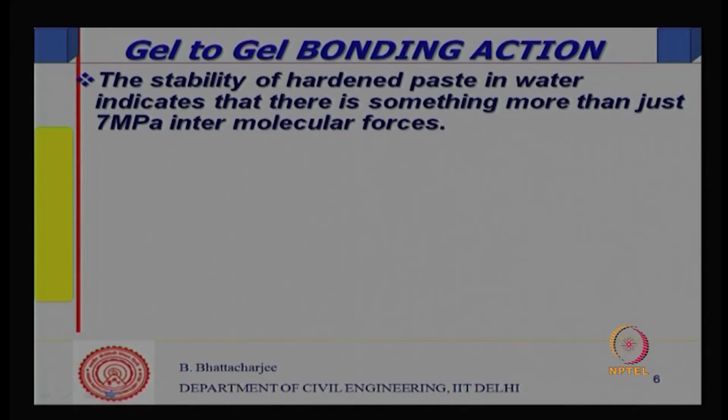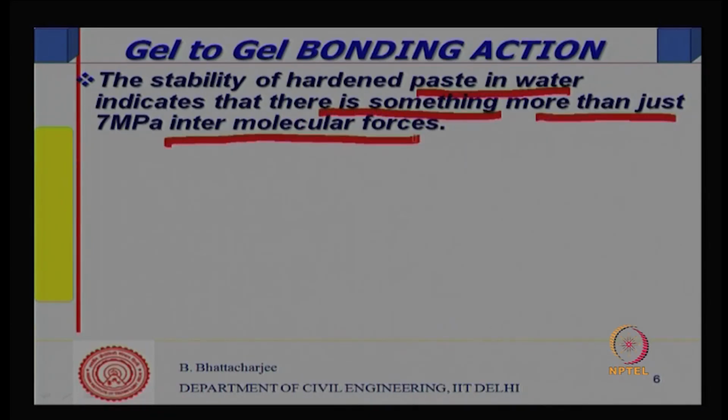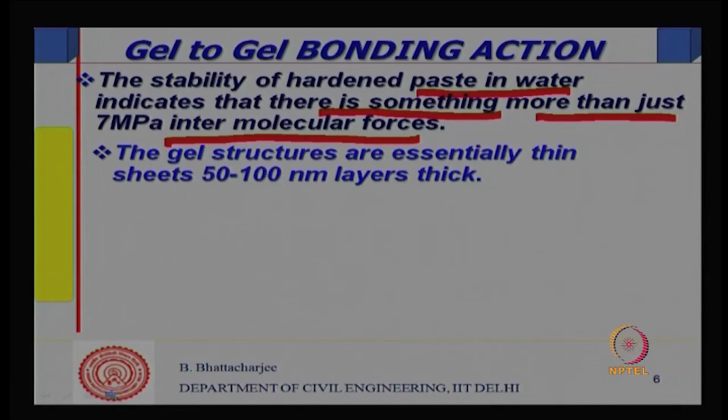Now, van der Waals bond or intermolecular forces cannot be the only force which is bonding them, but by and large this is the force. So, stability of hardened paste in water indicates there is something more than just intermolecular forces which holds them. But nevertheless, that is the major force understood to be responsible for strength of gel to gel.